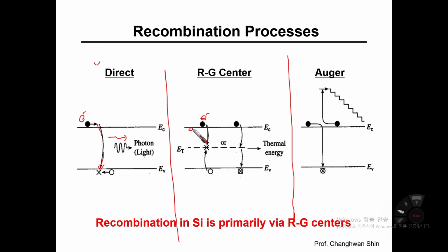In this case, the energy state induced by the defect is at half the band gap energy. So the newly created energy state is placed at the mid gap. And again, here T means a trap. So this free electron would be trapped, or get into this trap, this specified site. And this hole is also trapped and captured into this trap.